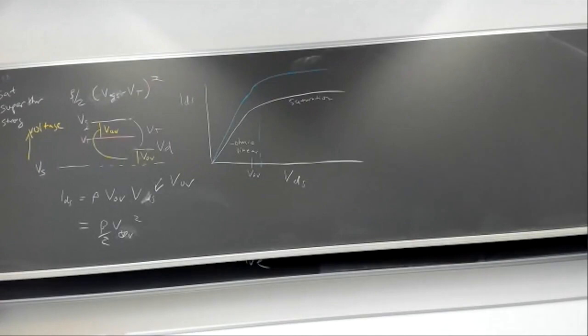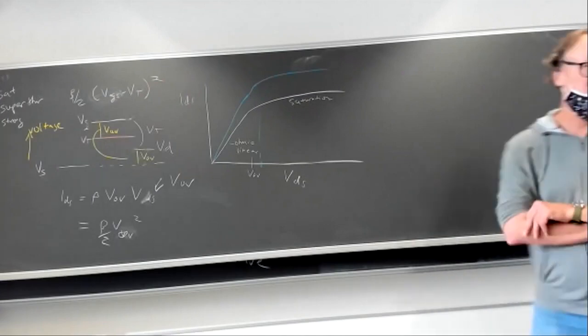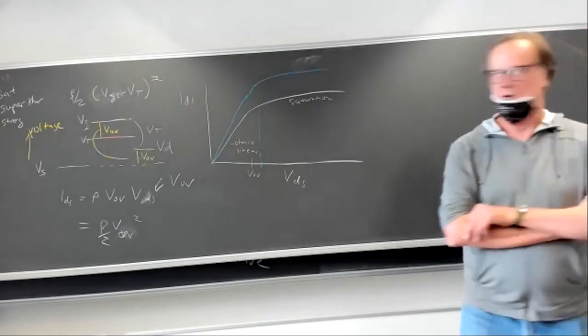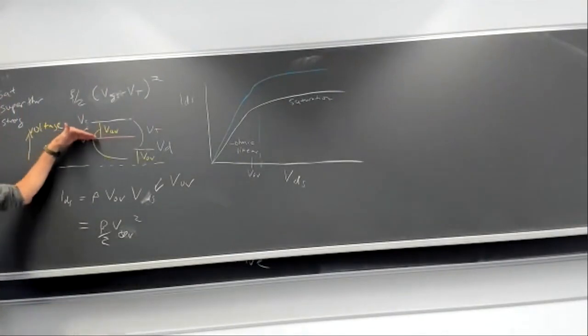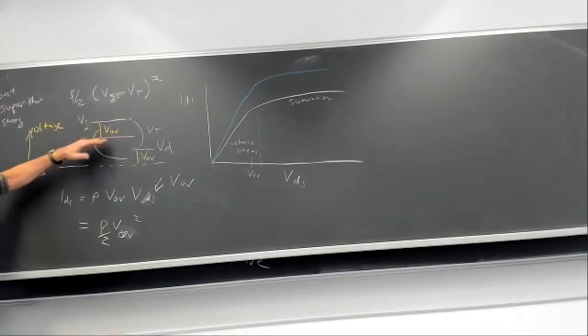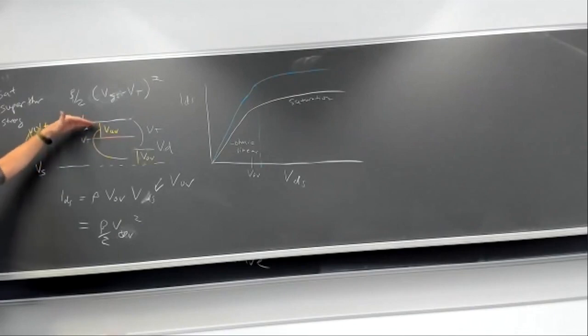5 minutes. Could you further explain, like physically you went before, that when it saturates, it's because the drain goes out of inversion. What does this mean? Right, the drain goes into weak inversion. It's not inverted anymore. Okay, you understand that the channel is inverted here, right? Here, the gate is above the threshold voltage, so you have a sheet of charge at the channel. Right? That's because the gate is above the critical voltage, the threshold voltage, and now the charge rushes in here.